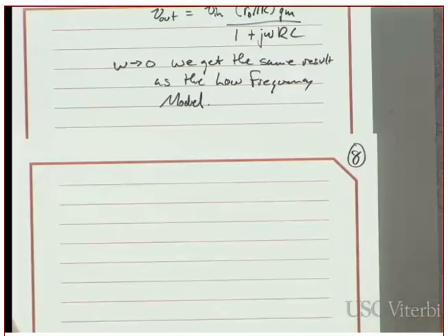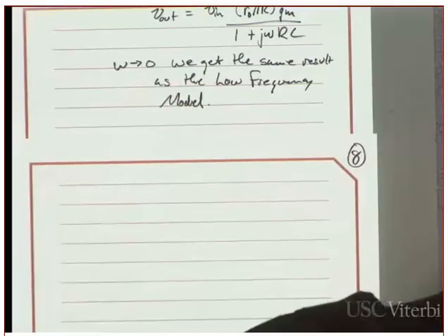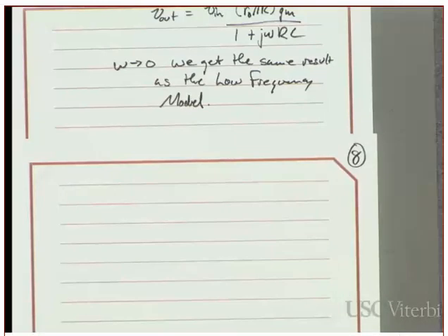And a lot of times what you'll see is a book will give you a certain model for a source follower, or a certain model for a common gate, or a certain model for a common drain. They all come from the same small signal model. They've just rearranged the components to make it look simpler. So let me show you the circuit that I'm going to use, and then I think I can get through a couple of those simplifications, and then I think I'm going to have to stop.